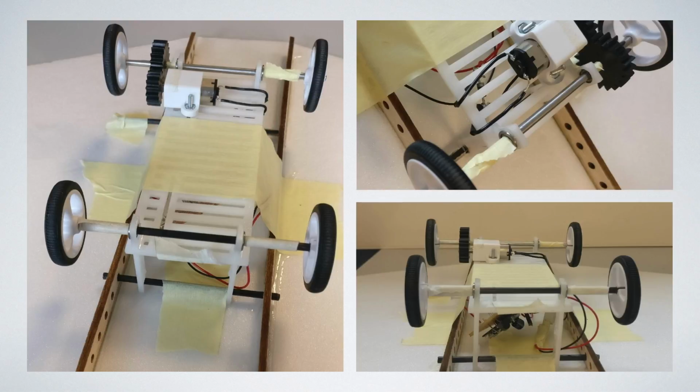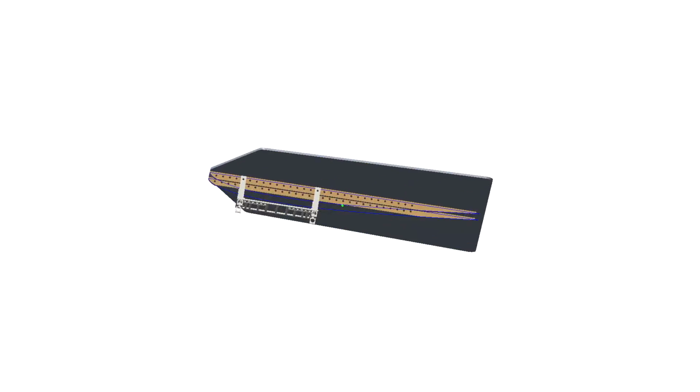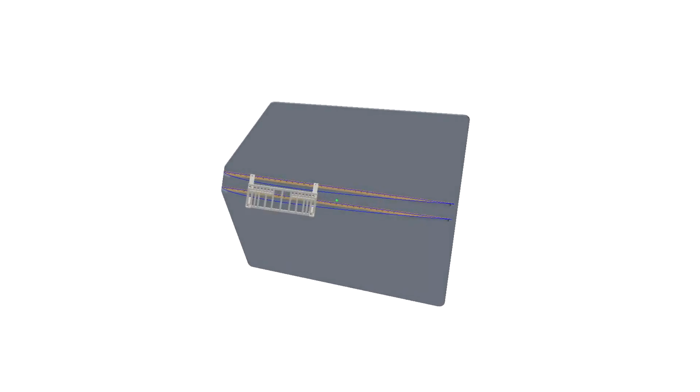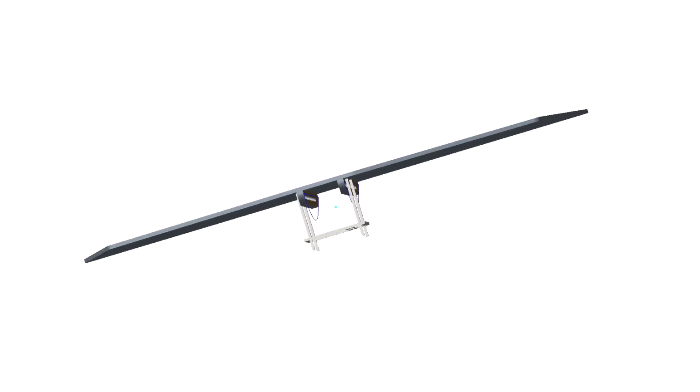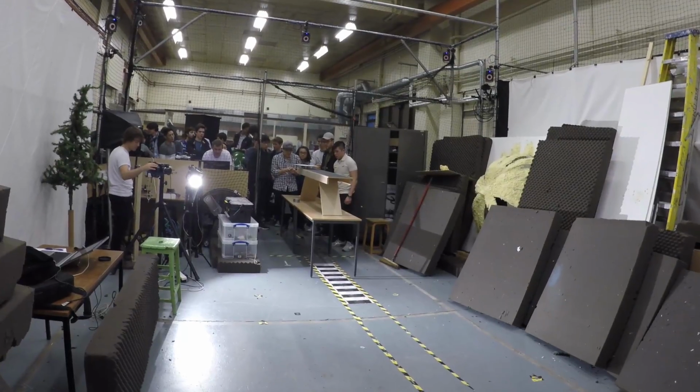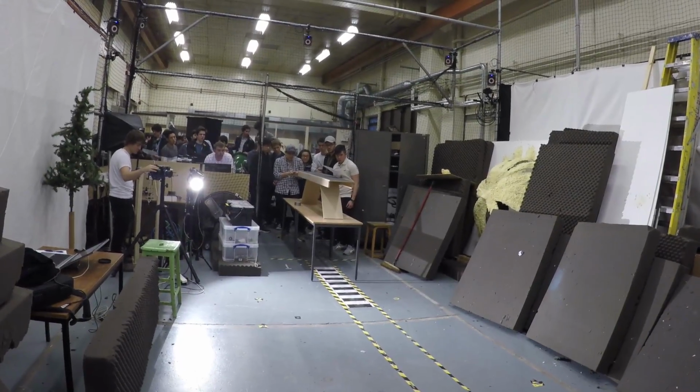The connection between the wing and the drivetrain should be improved to ease the change of the CG position, as well as access to the controller board for maintenance reasons. Precision during manufacturing and assembly should be improved as well, with closer fits to prevent the previously mentioned turning behavior. Last but not least, more testing, especially in optimal conditions, would have a great impact on the achieved result.